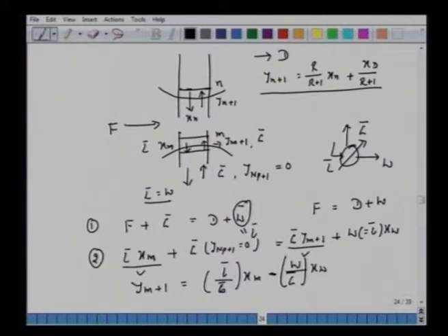Here there is no reboiler, so this product L bar is nothing but the product W. So these are new equations where L bar equals W. We see one modification in the overall balance, and the difference equation format is the same except that L bar is the same as W.